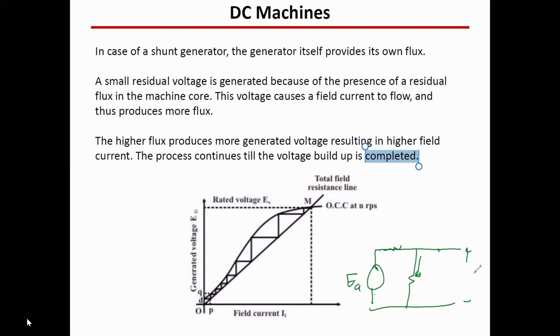So imagine that this is a brand new generator and you are providing the mechanical input. So it is there. And you need to generate terminal voltage. How do you do it? Because you need also magnetic field coming from here. And here the current is 0 because when you start the machine, the voltage is 0. So what do you think? How can we provide field current to this field winding? Maybe using a battery. Correct. Yes, a couple of concepts here.